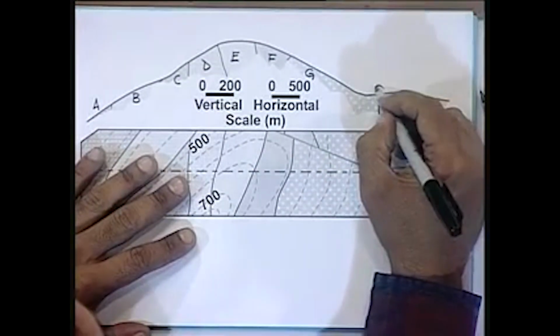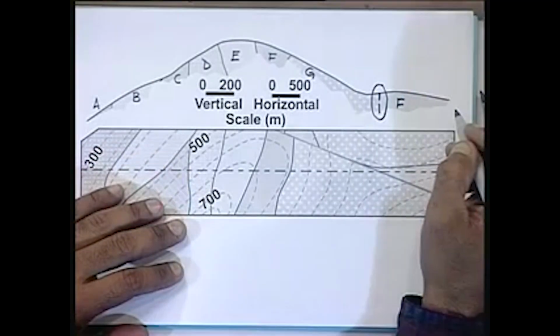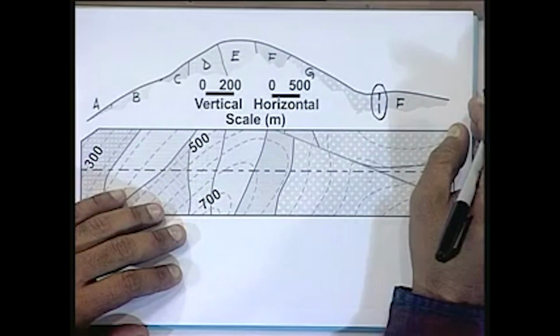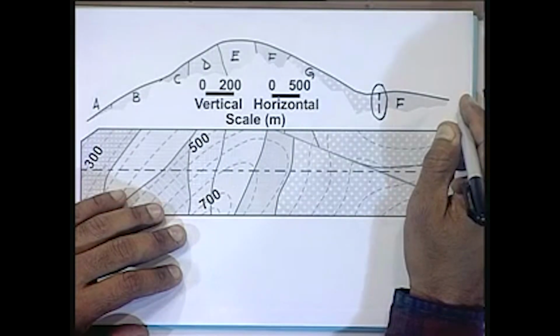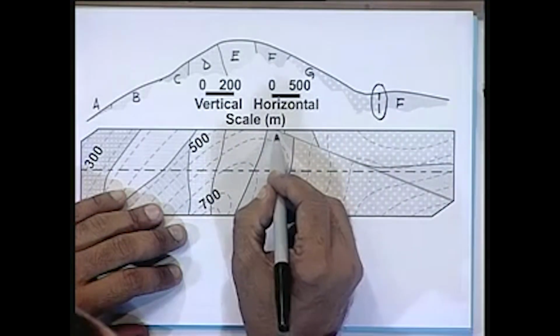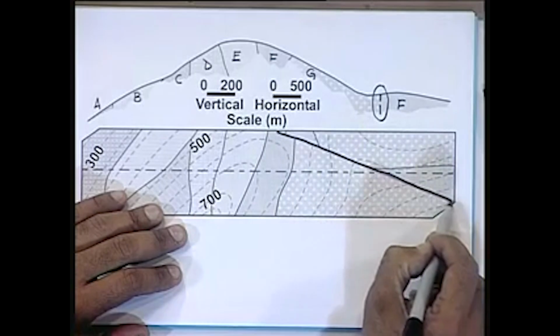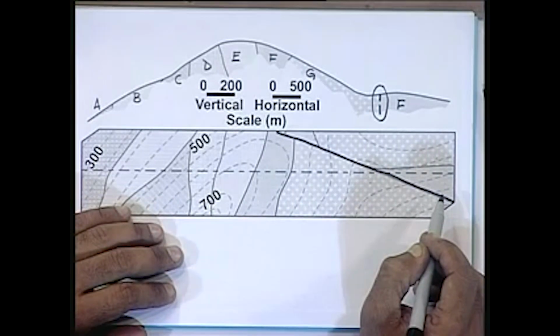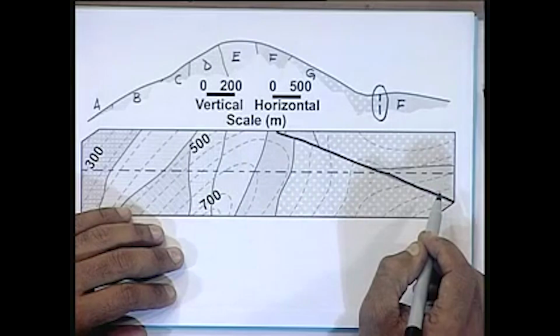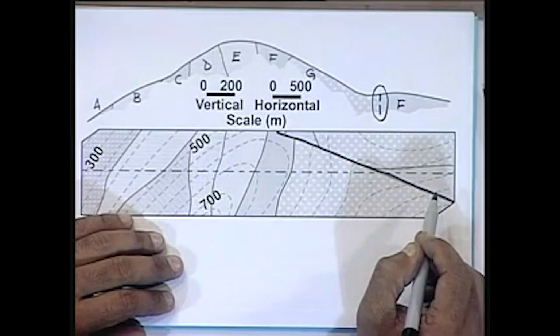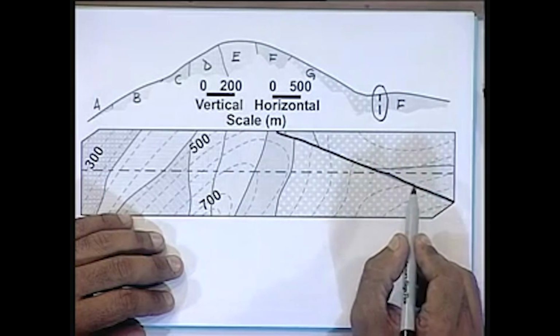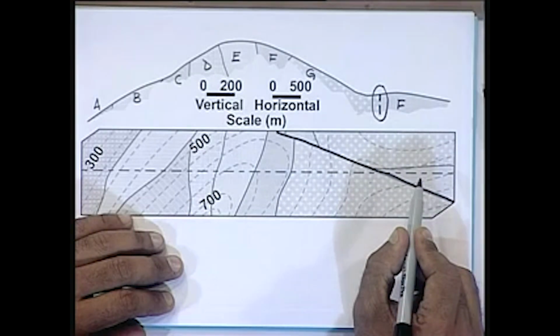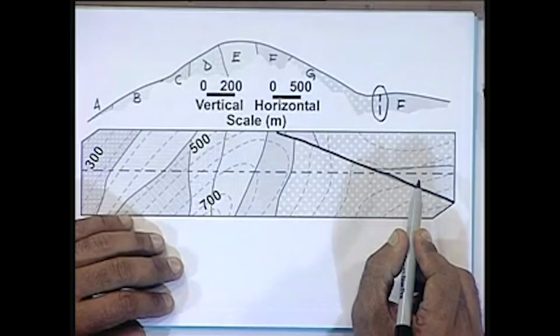Now you notice here that we have drawn the fault line in a vertical manner, because that is going to be most probably the case, because in this particular section the fault line follows a straight geometry in plan, and if that happens, then more often than not the fault line dips very steeply. As a result, we assume that the fault line in this particular case is vertical. But in general, in order to resolve the dip of the fault, you actually need some additional subsurface boring information in order to confirm the inferred dip of the fault line.